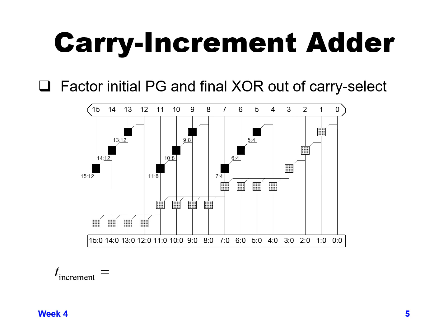A different way that you could do that is, for those 2 sums that you're calculating, there's actually some P and G logic that is in common that could be shared between those two sums. You don't need to do two full adder sums per bit. You can do the PG logic the same for each bit, and then you could have the final sum value separately for each carry in 1 and carry in 0.